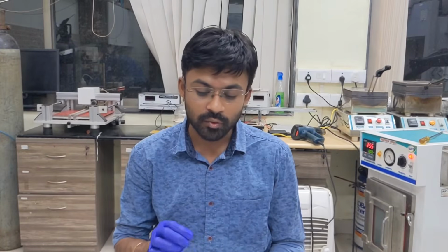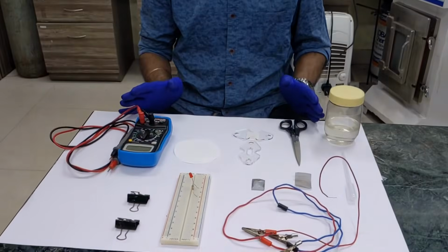Okay, so now I will teach you how to construct the zinc air battery. But before that, let me tell you one thing which is very important. Since the zinc air battery that we are constructing is a rechargeable cell, but we will only be doing the discharge process in this experiment, please do not try to charge it with any DC source available in the lab or the main source.